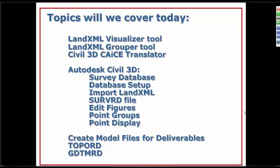We're going to talk about why and when we would use a SurveyRD file, which is a template that's part of the FDOT State Toolkit. We are then going to talk about editing survey figures, and take a look at point groups and point display. Once we've got all our data collected and cleaned up the way we need it, we're going to start assembling some model files for deliverables, the TopoRD and the GDTMRD file.